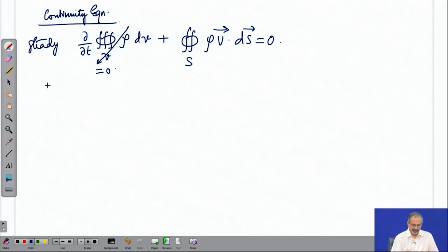flow, you can define a control volume which just follows the internal surface of the passage, and you are trying to figure out how the fluxes have occurred across the boundaries. Now, we notice that along these curved surfaces, everywhere if you look at it, the surface normal points out and the velocity is tangential. Therefore, they are orthogonal and hence a dot product would yield a 0.